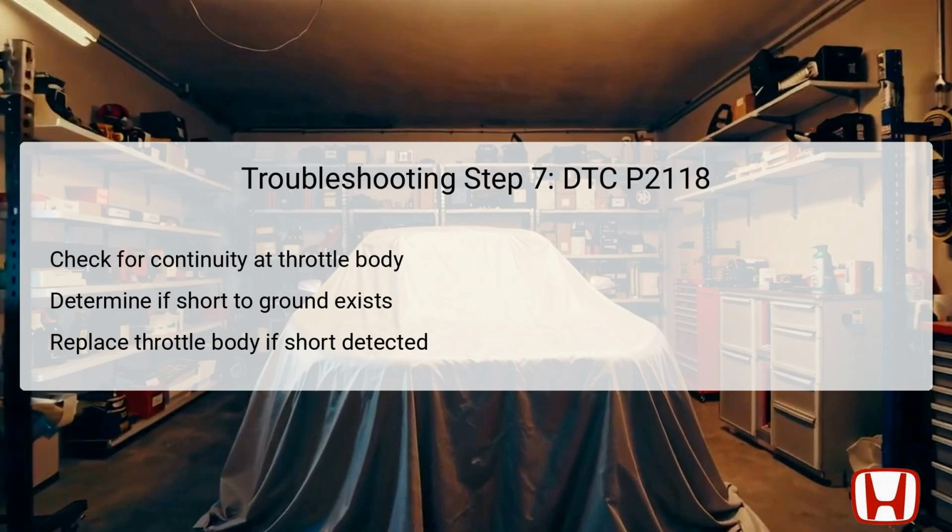Conversely, if no continuity is found, the technician is likely in the clear, allowing for an assessment of alternative issues. At this stage, substitution of a known good powertrain control module, PCM, or cross-reference with authorized service information related to DTCs could be the next logical steps.